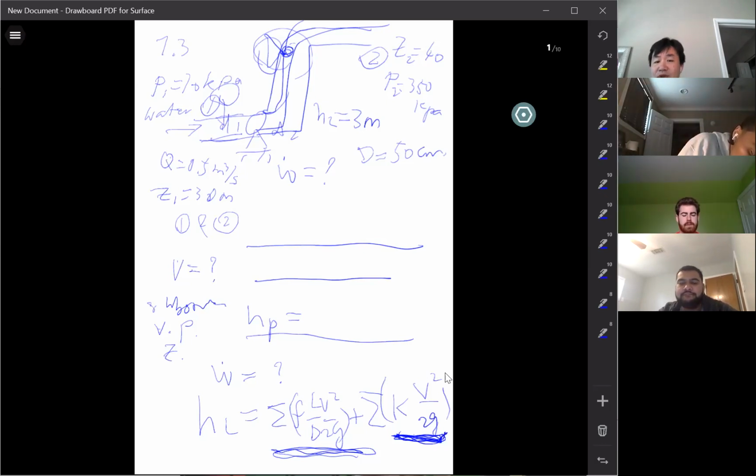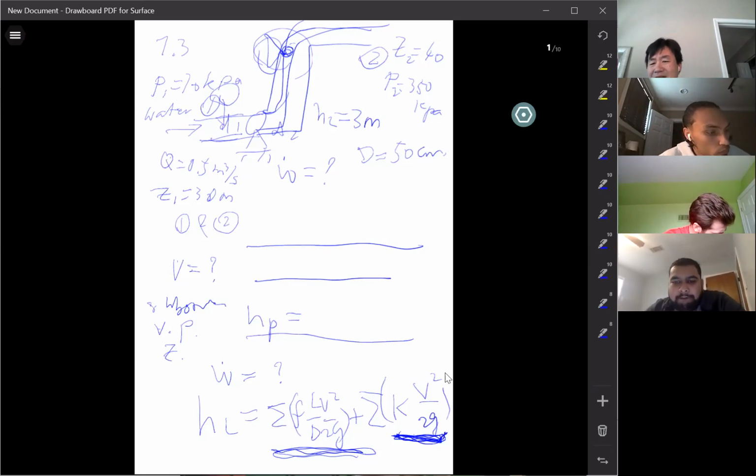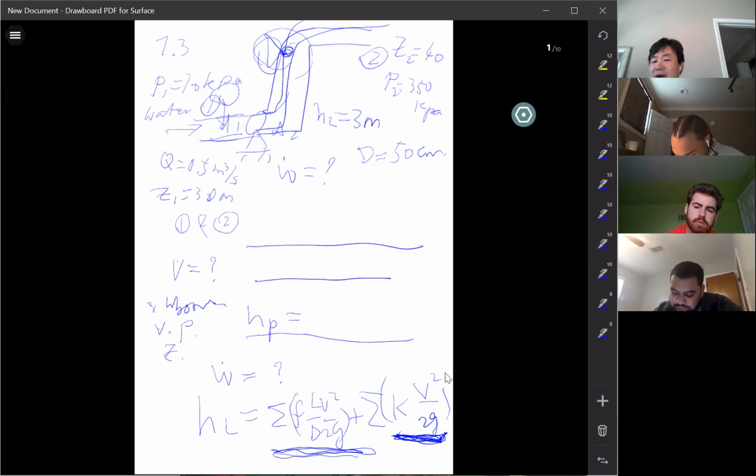In practical problems in industry, if you get a job there, they have hundreds of different portions of pipes in a system, very long and very complicated. What if your boss asks you to calculate the loss for the whole piping system? They give you the information already. If they change the size, you have to treat them as separate portions. For each portion, you look at the length, diameter, and velocity, find the F, and calculate the loss for that portion. Then move on to the next portion.